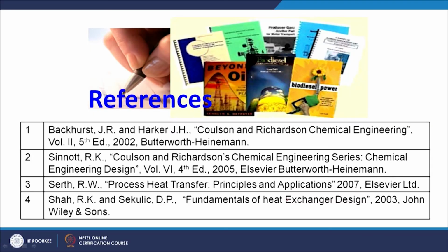So it is not possible to put the exit nozzle on the second side or the rear side, fine. In a common heat exchanger like fixed tube sheet, you can put the exit nozzle at the rear side also. So there we can have an odd number of passes also, but usually we consider inlet and outlet at one side only, and therefore the standard we follow is an even number of passes in tubes, right.